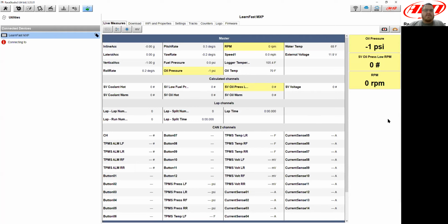And you don't have to click it on the side, but as you're doing there, I think is the best way. You can also hover over that gear and select to force. So now that we've got these values here, and we don't even need them over here. If you go on and watch them here, that's fine. But now we've got the little cog, gear here where we can go in and click on that, and we can what we call force the channel. And this is very, very powerful for your testing of your shift lights, and while you're sitting in the car, have your laptop sitting there, and you can do all these things.